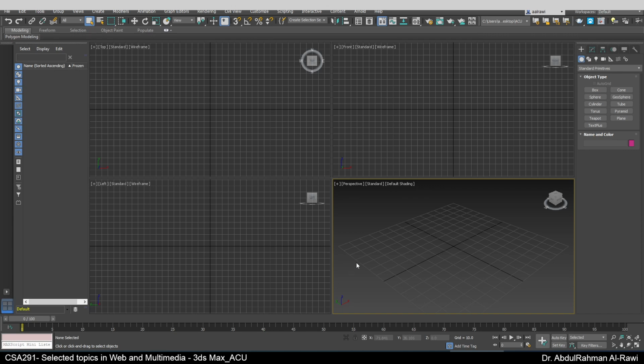Okay, so we're going to do the same thing in 3ds Max. We're going to set up a folder for our project where we can save, by default or at the beginning, the .max file, and then we can also save images or bitmaps, for example, for materials. We can link other files that can be imported or merged into our 3ds Max file.